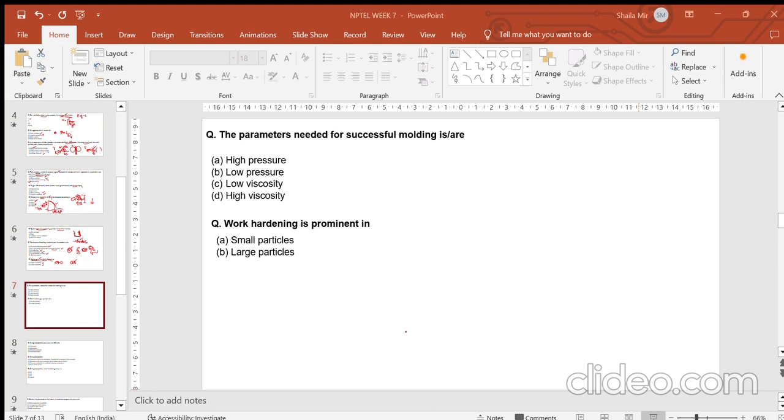Remember, all the units have to be given in standard SI units. So this is 800 mm, so this will be 0.8 meters, and this is 60, so this will be 0.06 meters. So you can put the data here, 0.8 minus 0.06, because we are given this is a diameter, so we can multiply it by 2. We can calculate the critical speed of the ball mill.